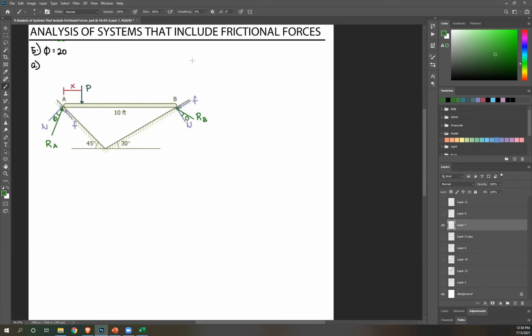Let's try starting with RB. So just follow the direction. RB is somewhere like this, right? Next, RA is upward. And the only thing that's important is to make sure your drawing follows orientation and it closes. So if this is your RB, RA is this way, and then P is downward. So you have a triangle, and then equations for triangle will apply.